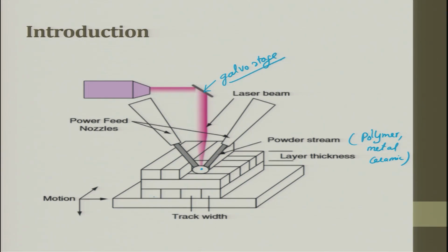And here you can see these are the track widths. The track widths, it is pretty interesting. You can see the direction of the track widths also changes. So, it is 0 orientation, this is 90 orientation, maybe you can have 45 orientation, whatever it is, and we can start building up the product. And here, since it is made out of metal, it can be used for real time usage, or this part which comes out is an example for rapid manufacturing.